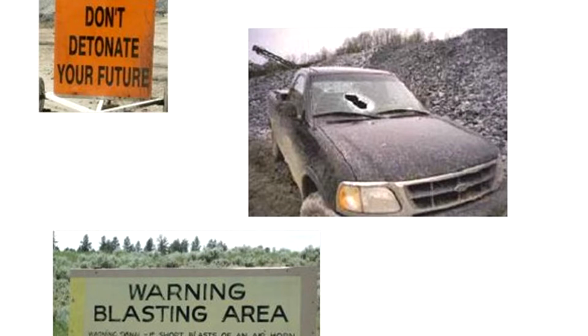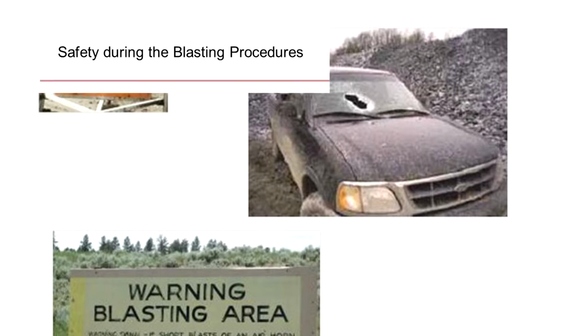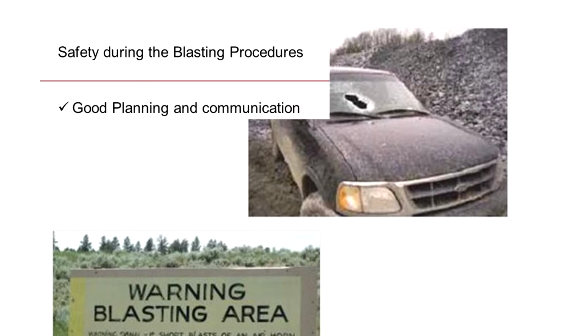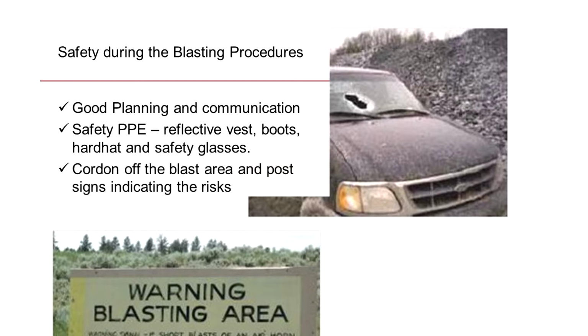Remember that blasting is a dangerous exercise and safety precautions must be taken at all times. In the quarry you need good planning and communication, safety PPE: reflective vest, boots, hard hat and safety glasses.